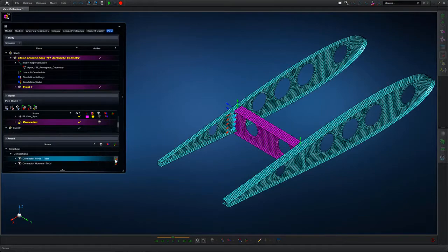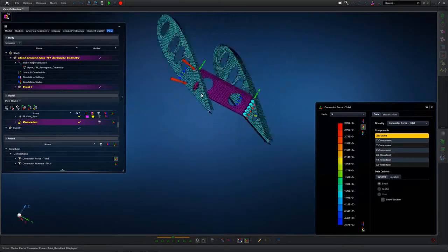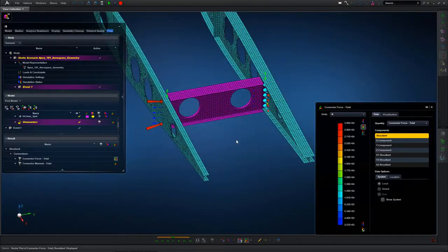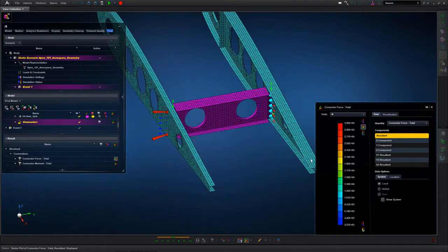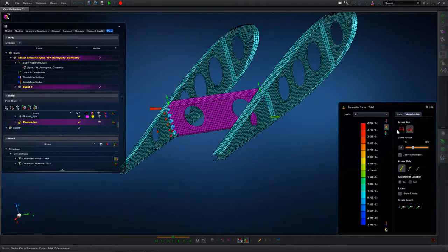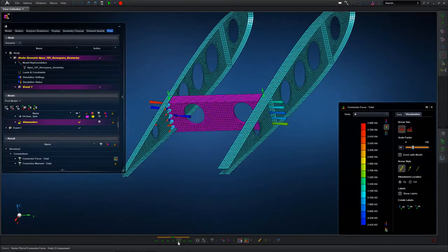and then we've got full control of the connector forces and or moments, and we can plot the vector value on a resultant or component level based on the load that's transferred through those fasteners. So again, we've got scaled views turned on, so we can see the larger vectors defined. If we set it to uniform view, you can see the lower values that are attracted to each one of those fasteners, and we can animate and cycle the load through to see how those loads are being distributed through the joint.